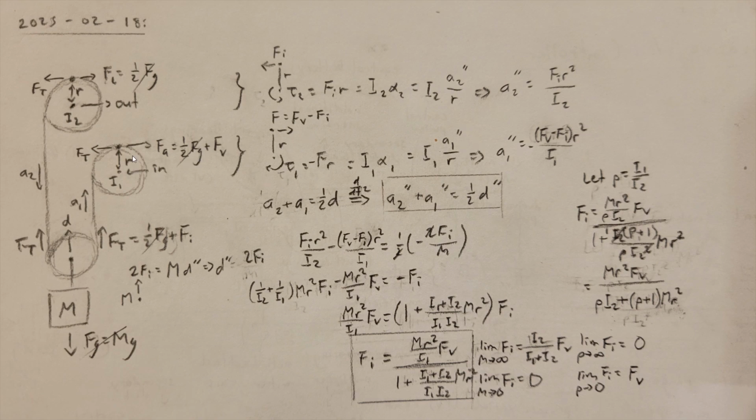The Huygens Drive was originally designed to have the input sprocket locked most of the time, while the tension from the mass drives a constant load of a clock escapement, the force disturbance from lifting the weight only happening every few days. Since the mass is allowed to fall, it is allowed to apply a constant force over a distance and hence do work. In your design, we try to keep the mass's position constant, so it does not move and thus cannot do any work toward maintaining the machine's speed. Therefore, almost all of the work is being done by the user, while the only work the mass can do is to slightly filter the input fluctuations.